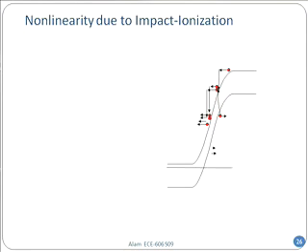It's like one skier is standing on the top of a mountain. Now that electron comes in, if it is not scattered by the phonons, which is lattice vibration, then it can have a certain amount of energy, right? If it has enough energy larger than the band gap, and in fact it turns out 3/2 the band gap. Yeah, it's 50% more than the band gap.